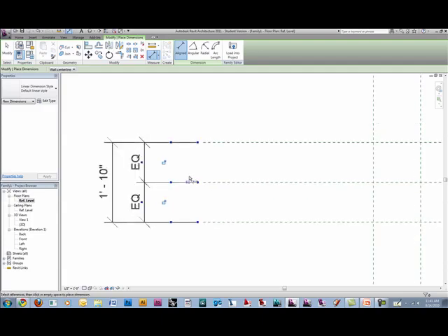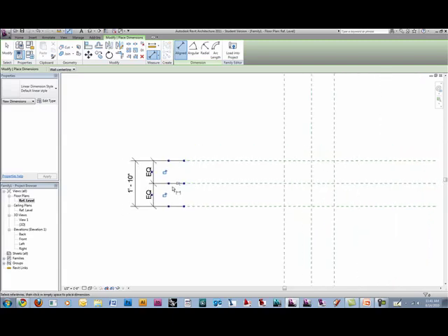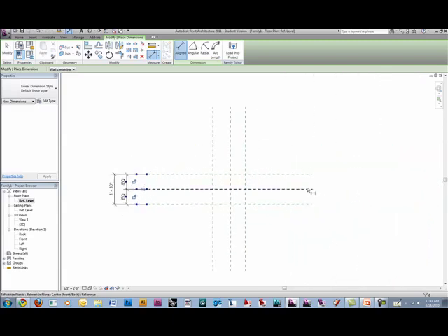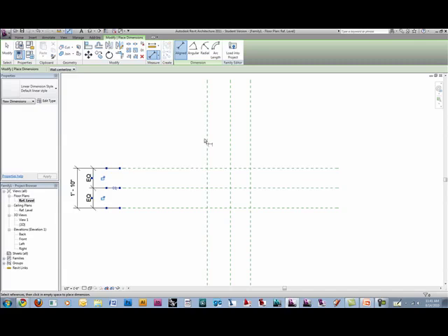The equalize symbol will put the lines equal. So now these lines are perfectly equal. You don't want to lock them, no, because then you can't really make it parametric still. Locks would be used if you're trying to constrain it like 3 inches off a wall or something.